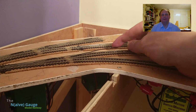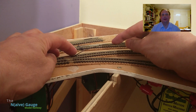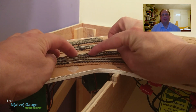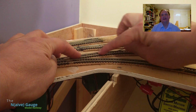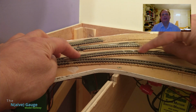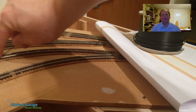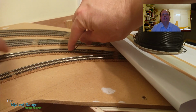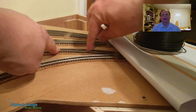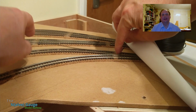Now, I've worked out how long they should be when I designed it, but there's nothing like actually measuring what you've built. So I'm going to take a piece of wire here and just run it along the outside of the inside rail. Now that's not quite along the centre line, but I can measure how far away from the centre line it is and then do a little bit of maths to calculate what the error is going to be and add that to the total length.